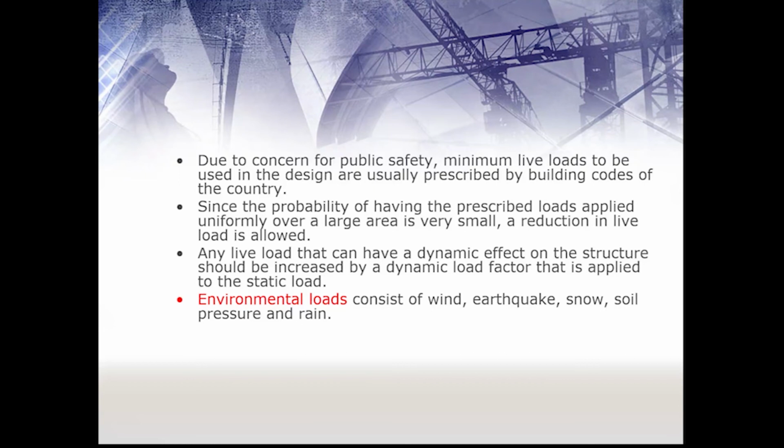But since the probability of having the prescribed load applied uniformly on a large area is very small, a reduction in live load is allowed. In some design codes or building codes, they specify the load, and they will also explain, if you want to apply a reduction, which reduction factor you have to use for a certain type of live load. And these reductions also depend on the type of structure you are designing.